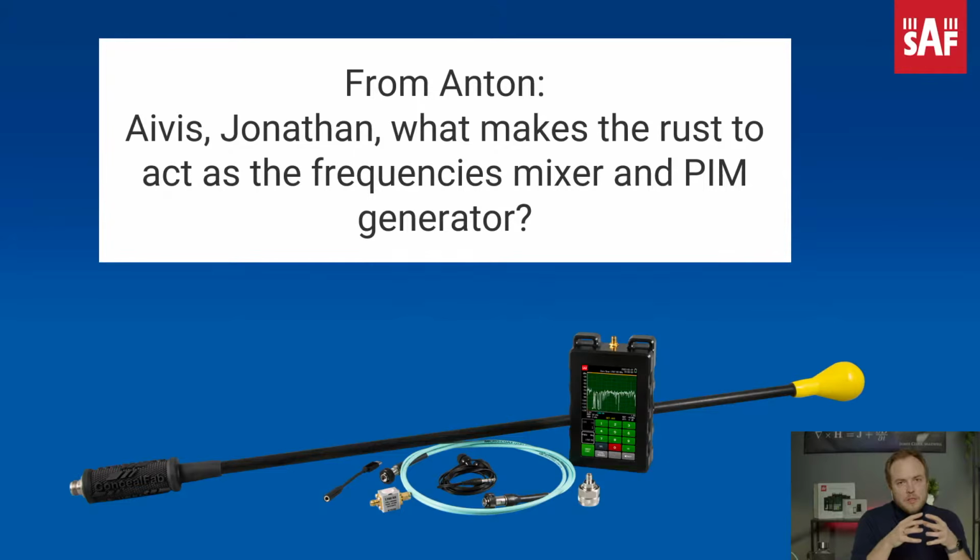This creates a non-linearity in this element, and it basically becomes a passive circuit, and this is what creates the PIM. From the name, passive intermodulation, it means the combination of those frequencies happening in a passive element, which is not powered with anything.